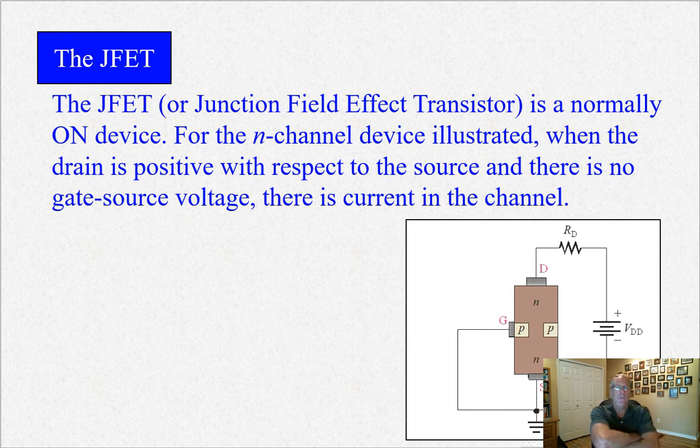So here's the JFET, junction field effect transistor. That's the first kind we're starting with here. And it's a normally on device. So if you don't know, there are three terminals here. Drain, that's what the D is. There's a gate, and that's the source. These things going up here are actually holes. I believe this is an electron flow model instead of conventional current model. But be that as it may, it's still a three-terminal device, just like your BJTs.